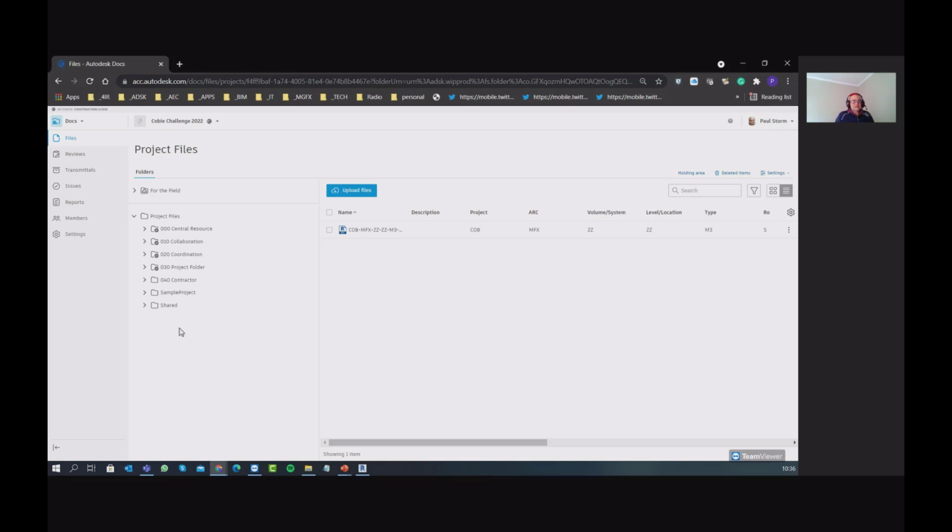So for instance, in Revit, that's easy to understand. I think, Sean, you also use Revit, right? Yeah. So with Revit, you and I would be able to work on the same file at the same time, just like a central file on a local area network, and we'll be working through the internet. And then once we publish our file, that's available then to our team. And then after that, we have to share a package with the other teams. I can show you what that looks like.